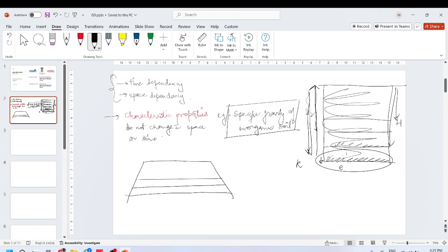So in that condition, you get a kind of stratified deposit, and this stratified deposit has a different permeability in this direction. It has a different permeability in this direction. It has maybe different properties in x and y direction. That is why in seepage nets, you study the anisotropic seepage net also. It is because of the way these embankments are constructed, you get a stratified kind of deposit that may have slightly different properties.